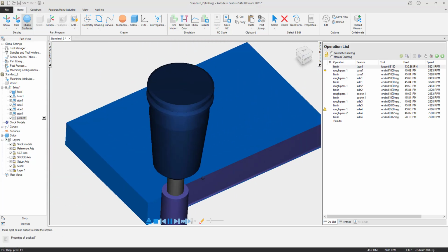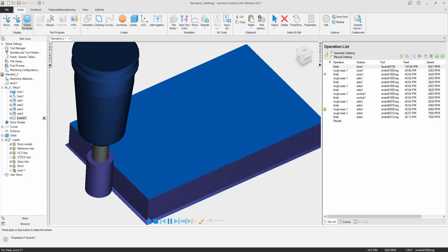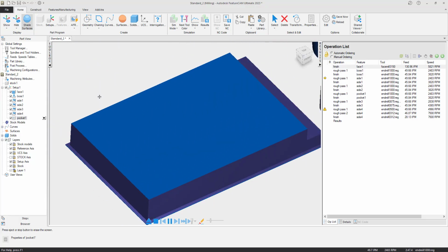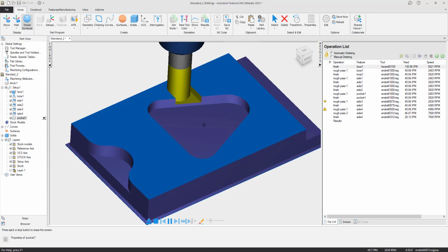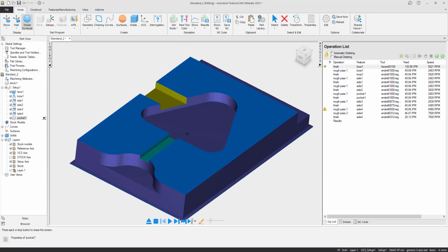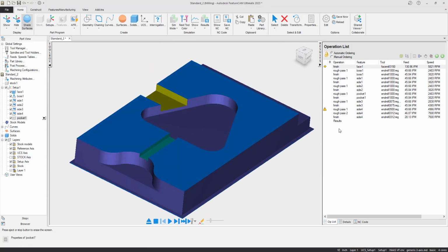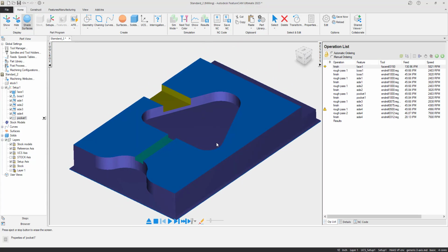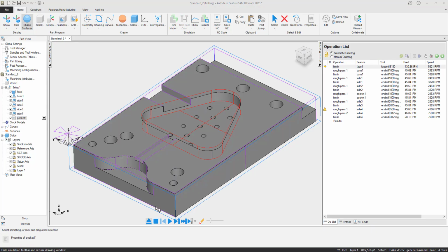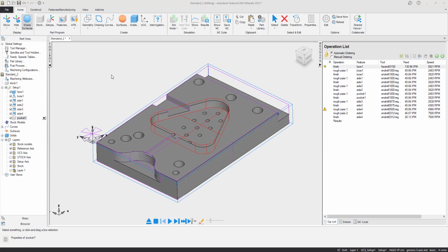So notice we're going through it really quick because we want to see these features generate the right toolpath. And once these toolpaths are generated, we're going to go through and start editing a little bit of it. So notice how it put the pocket in there first. Now it did that automatically. It did an automatic reordering because it wants that pocket gone so that these tools will be less likely to get buildup when they're cutting or whatever its reasoning was.